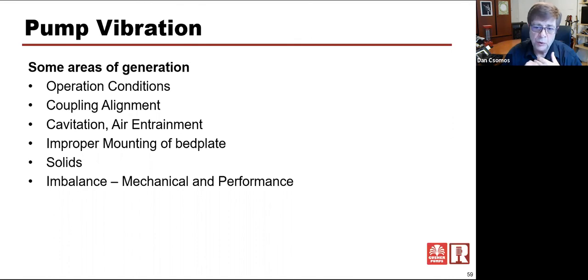If you have a solid come through a pump, and let's say it bends one of the 6 vanes on that impeller as it's going around, well, if that one vane is bent, it could be bent outwards or bent inwards, it's going to do either more or less work as it's spinning at 1800 RPM in rotation.